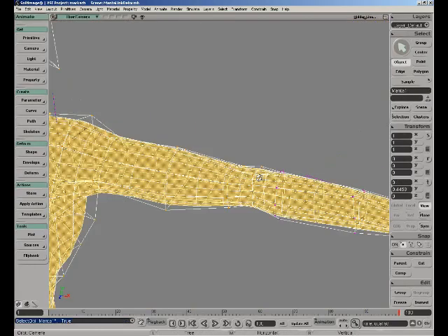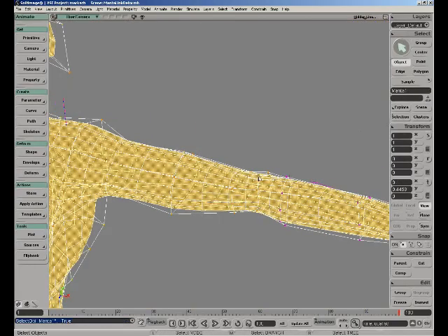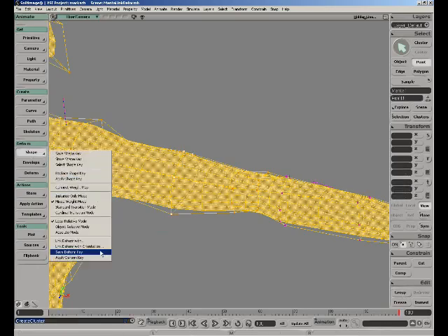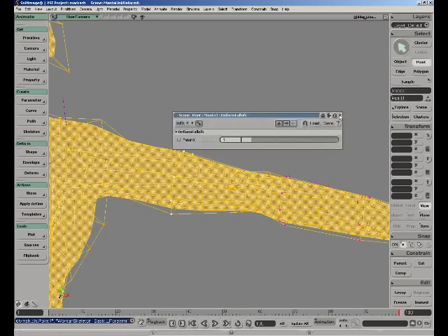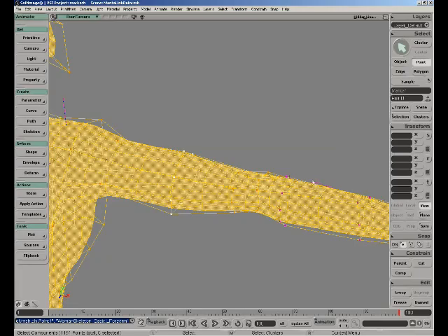So the first thing you want to do is define the area that you're interested in deforming. In this case, it'll be these tag points which will make up the bicep. So tag those points and turn them into a cluster. Now with that cluster selected, simply say Shape, Link Deform with Orientation. You can also choose Link Deform With and choose from a list of other parameters other than orientation. But since orientation is usually the most popular, we set that up as a preset. So now click on the bone that you're interested in linking that to, right-click to end that selection, and you've now linked the deform to that bone.